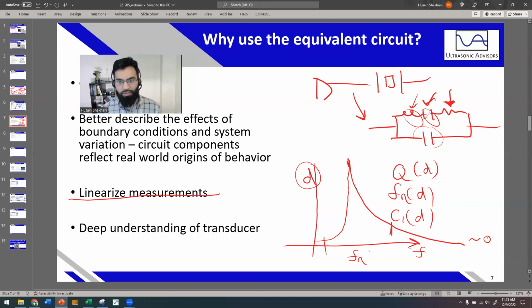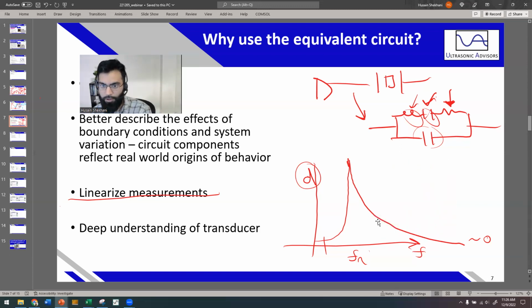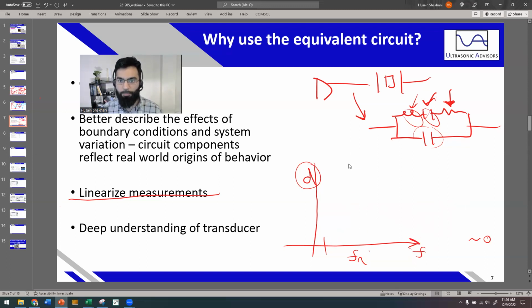But once you have any significant amount of voltage, you also have other parts of your system, your amplifier, playing in. So what do we do in this case? Generally, amplifiers have an output impedance. What this basically does is act like a resistor.